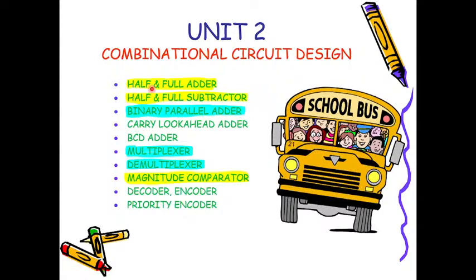To build these, you should know how a 2-bit addition happens and what circuit performs it. That is what we call a half adder. And if you have a carry generated from the previous addition, along with the present two input bits, how to add the carry bit, that is a 3-bit addition, which we name a full adder. The same applies to subtraction also.